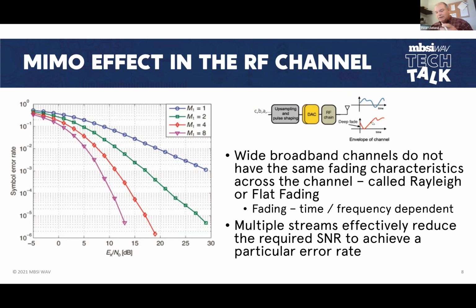It'd be wonderful if a transmitter puts out 1 watt, and at the receiver you're always going to receive exactly the same amount of power all the time. That does not happen. This happens where we have fading. We have other things that are occurring. We have fadings that occur on particular OFDM channels. We have fading that occurs actually in the streams, and they're different to each other because of the fact that the RF that's transmitted is different in the respect of the whole way MIMO works.